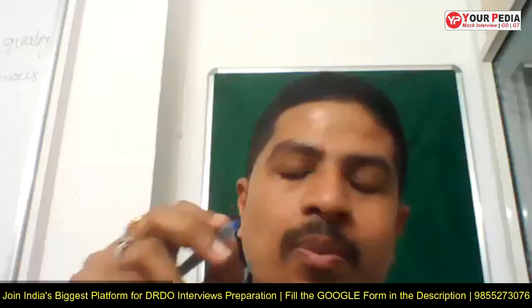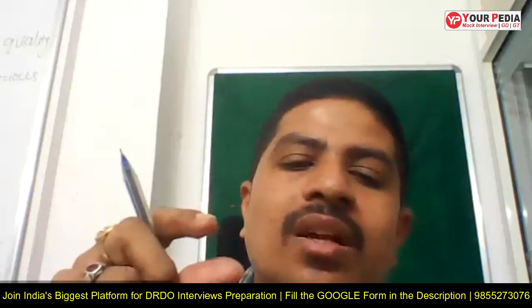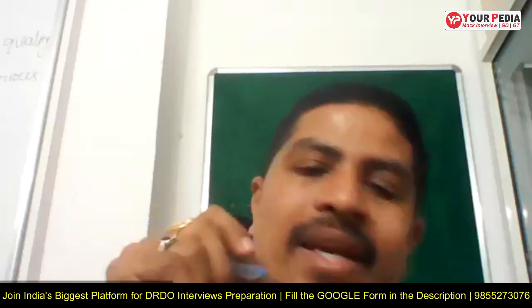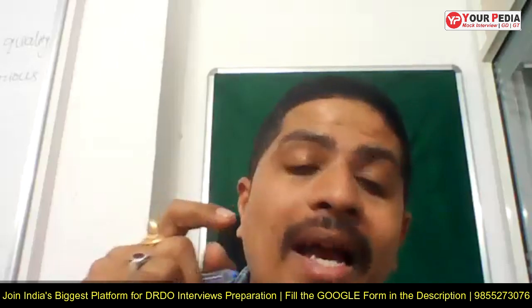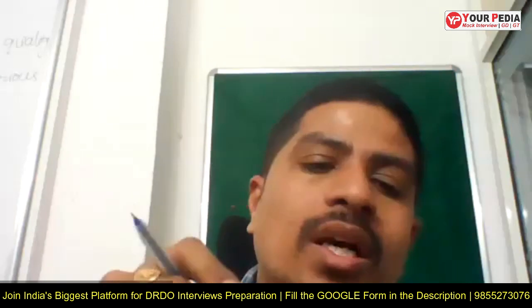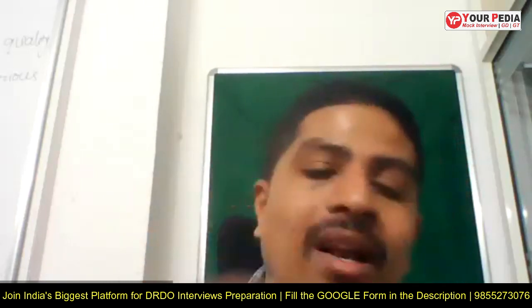Yes, sir. That point is a root of the characteristic equation, or that point is there on the root locus. So yes, that is a pole location. I'm going to get some transient response by looking at that root. But I want the transient response because of a root which is not there on the root locus, but is there somewhere on the straight line.